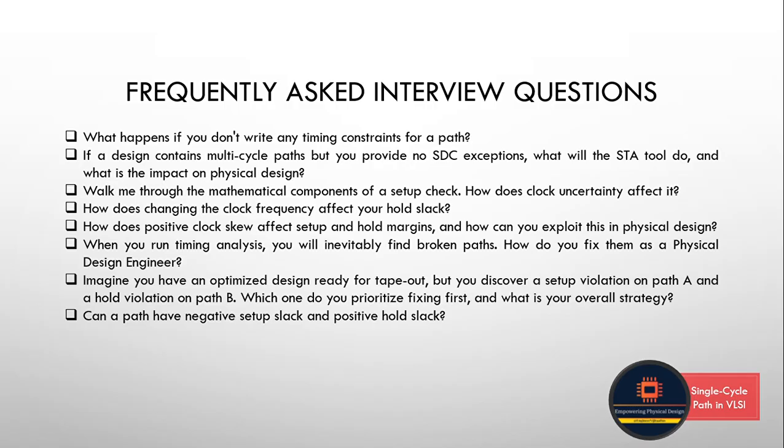So it can do anything. It is over constraining, right? It can waste your area, it can waste your power by upsizing the buffers, and high leakage cells can also be added. So that's one of the reasons.